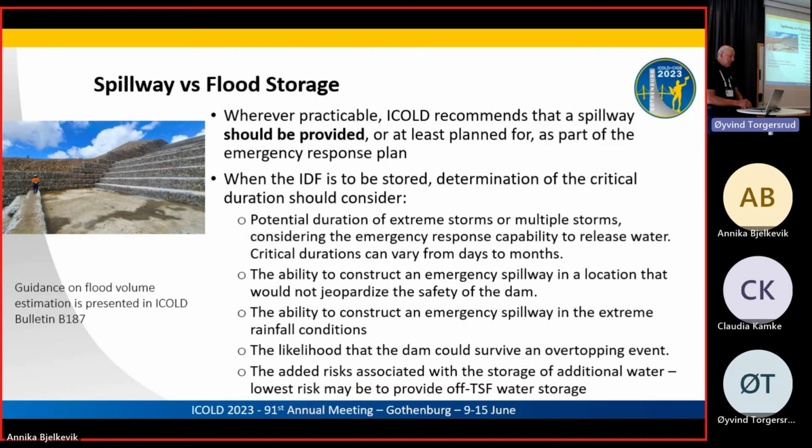If we do want to store the IDF, I think most of us agree it's probably not that desirable, but in some places we have to. We need to think about this question that Malcolm raised about multiple storms. It's a pretty controversial question about how much storage you really should provide. It's all very well to think about storing a PMF or something like that, but how long does it take you to get that water out? And what's the risk of some more water coming in while that's happening? So it's a pretty interesting problem to determine what sort of storage capacity you might provide on a dam if you don't have a spillway.